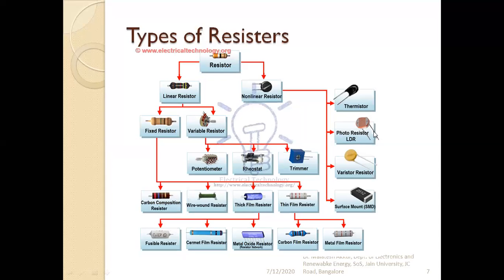All these sensors give the information in analog form only, that is, continuous with respect to time. But this analog signal cannot be processed by a digital system like a computer, so we need to convert the analog signal into digital. We use the A to D converter, the analog to digital converter.